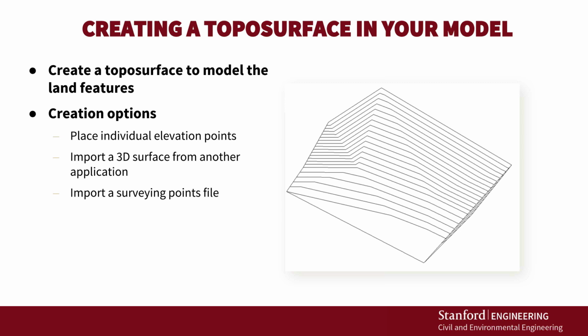We can place individual elevation points and create the topo surface from those elevations. You can also import a 3D surface that was created in another application. And finally, you can import a points file of surveying data.